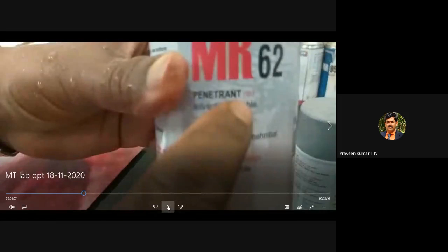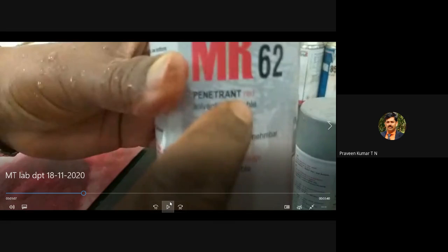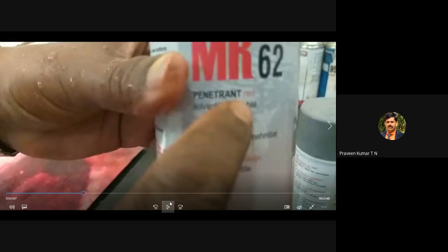You are using the term penetrant. You know what penetration is. We have a cavity, and when the red color penetrant is applied, because of capillary action, which you studied in physics, the penetrant penetrates into the small crack. That's why it is referred to as a penetrant. It is always red, so that we can identify wherever there is a crack on the surface. After removing the developer, we get only red color, and in those regions we can conclude that there is a crack.